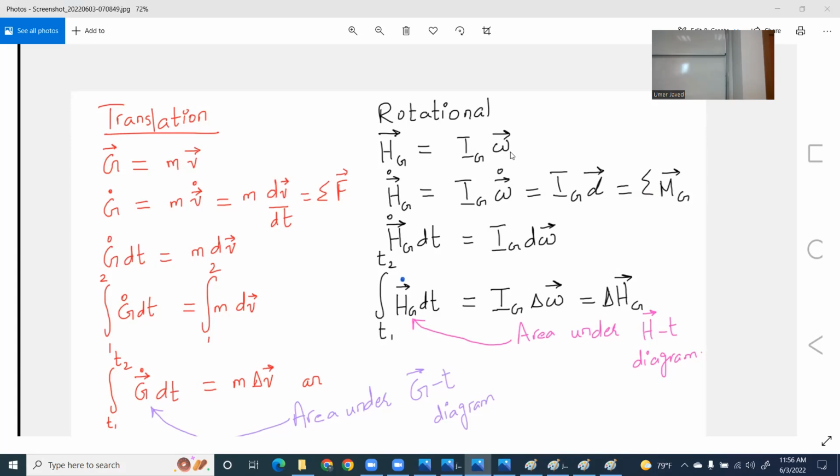Did I answer? Yeah, so we have how many equations? We have 3 equations. One is the kinematic equation, Ag equals At plus that vector. Then we have one equation with the summation of forces in the x direction. And then we have one equation for the summation of moments about the center of mass. So technically we have 3 equations, but I wrote only 2 because I incorporated the third equation in the first equation. Okay. So we found alpha and Ag, and therefore we can find F. Ag, alpha, and F: 3 things that we found.